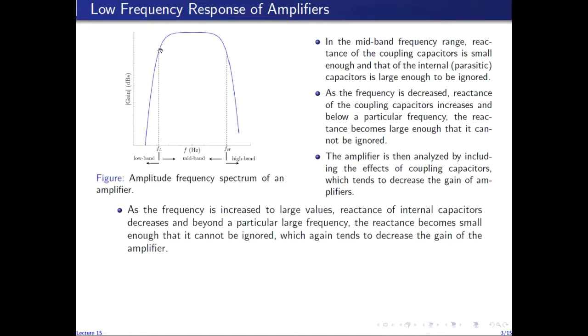So in the mid-band, we do not take into account the effects of capacitors. On the lower side, we take into account the effects of coupling capacitors on the response of the circuit, and on the higher side, we take into account the effects of internal capacitors on the performance of the circuit. So these capacitive effects, like I said, tend to decrease the gain below the mid-band value.